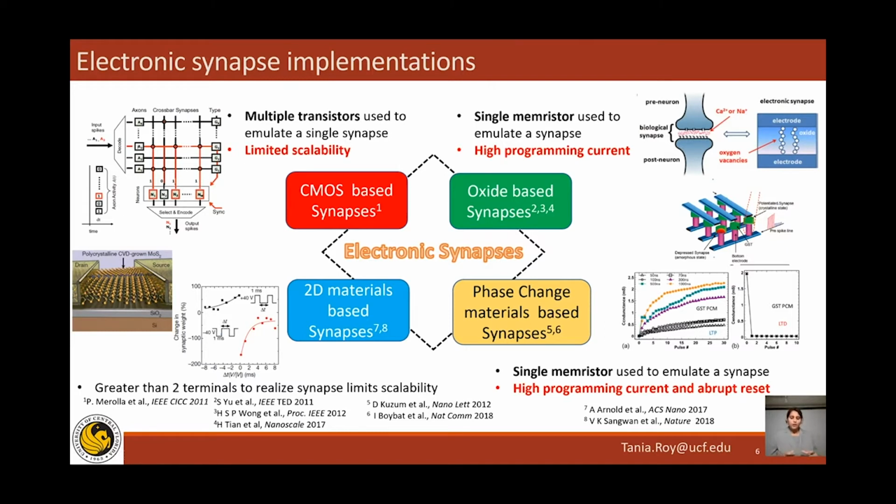And then recently, people are showing metal, 2D material, metal structures, which are also showing memristive effect. So the 2D material in between could be monolayer 2D materials, surprisingly enough, and also multi-layer insulators like boron nitride. So they are showing memristive behavior, which shows high prospect in using these devices as synapses.